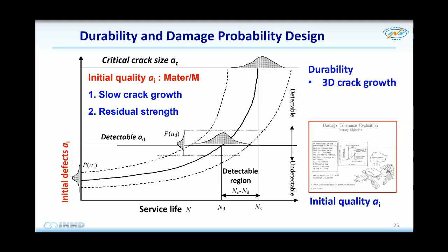So this is durability, or crack initiation usually. So this is always there. We can make prediction not only of the micro crack, but also below the detectable size, from this initial size. So we have initial, we can examine material, we can have initial quality, and we can do the prediction of durability of three-dimensional growth for the whole life.